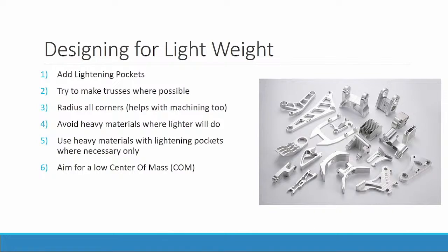Wood is known for having a grain structure. It has a stronger direction. It is not consistent. A different cut of wood will have a different strength than another one, as opposed to something like steel or aluminum, which will typically be more consistent throughout. So if you 3D print something, it will not have a consistent strength depending on the orientation. So maybe you need to move to aluminum if you can't.